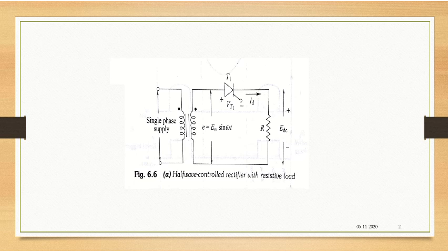Along with this, you also have the single phase full wave control rectifier. In the circuit here, you can see a half wave controlled rectifier with only one thyristor. Full wave means you can use two thyristors, as a center tapped type of full wave rectifier, or if you are using a bridge circuit, you will call it a single phase full wave bridge converter.